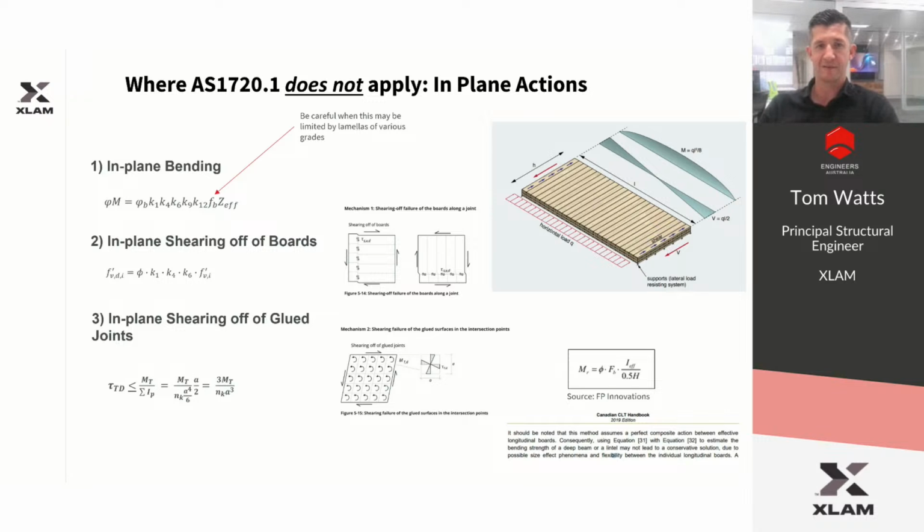But you also need to be careful that you're not treating it as a glulam beam, because it varies from manufacturer to manufacturer, but XLAM doesn't glue its edge boards. So you need to be careful that you're not making the assumption that this is acting directly like a glulam beam. Also, I mentioned earlier that XLAM features lower grade material on the inside of the panel. That needs to be considered in the residual strength, so that you're not assuming you've got higher strength material resisting those failure modes than you might otherwise have.